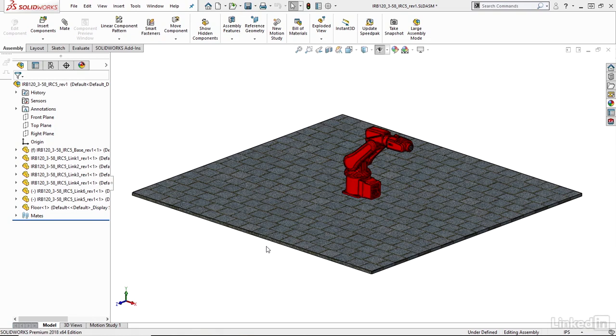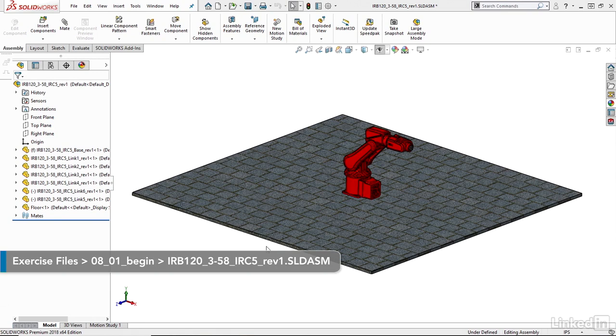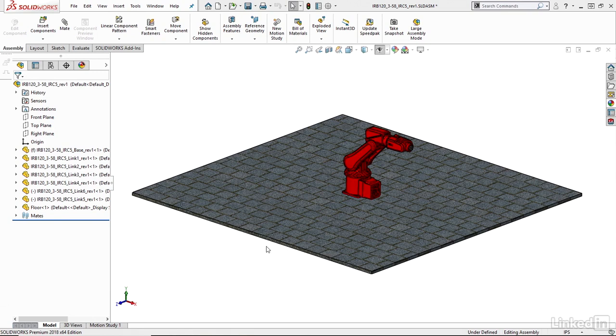Cameras can be used and added to models or assemblies to help generate more specific views from a camera perspective. The position and target of the camera can be specifically defined, as well as some more control properties, such as field of view and depth, to help generate more exact views.